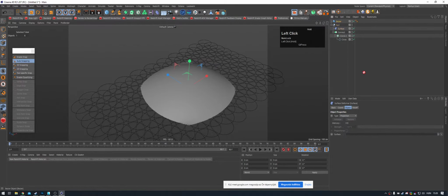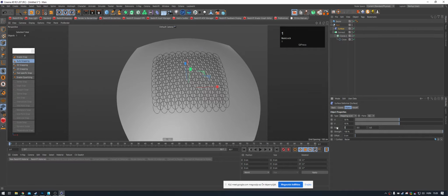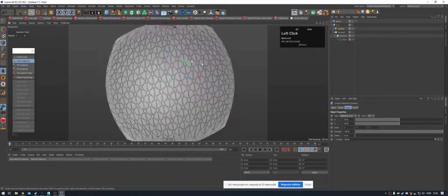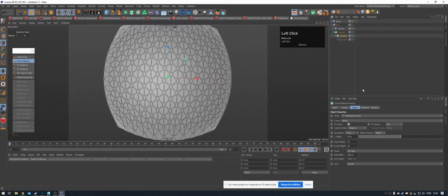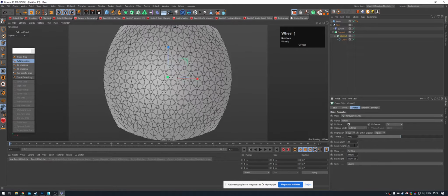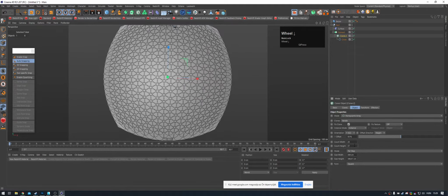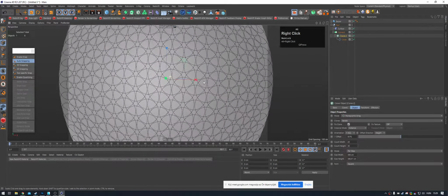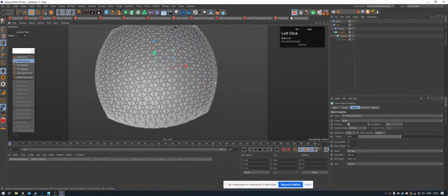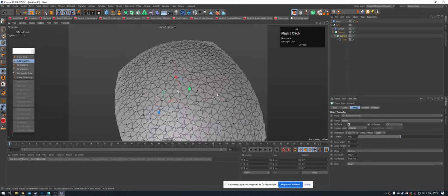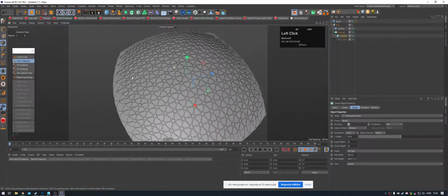And I put the Bezier surface into it, and instead of projection I use UV mapping, and I go for 1 by 1, and it's a little bit too distorted for my taste, so I increase the count width and count height to, let's say, 30. You know, because it's distorting, especially at the edges. It's beautiful.